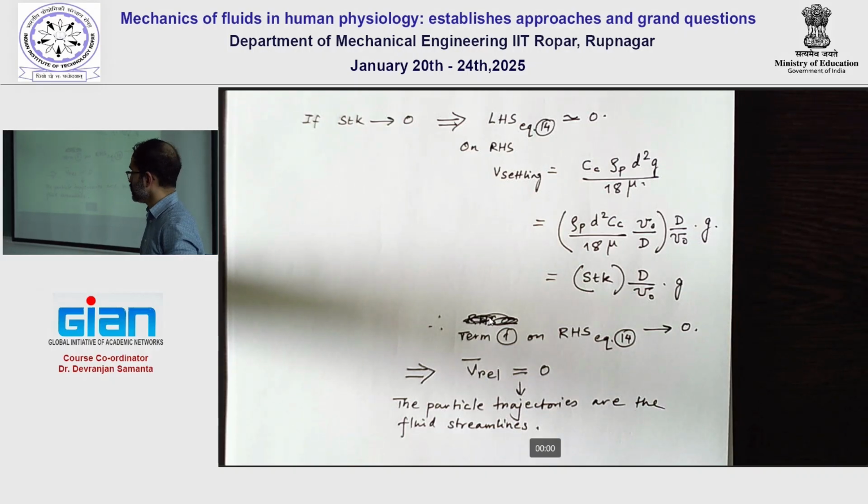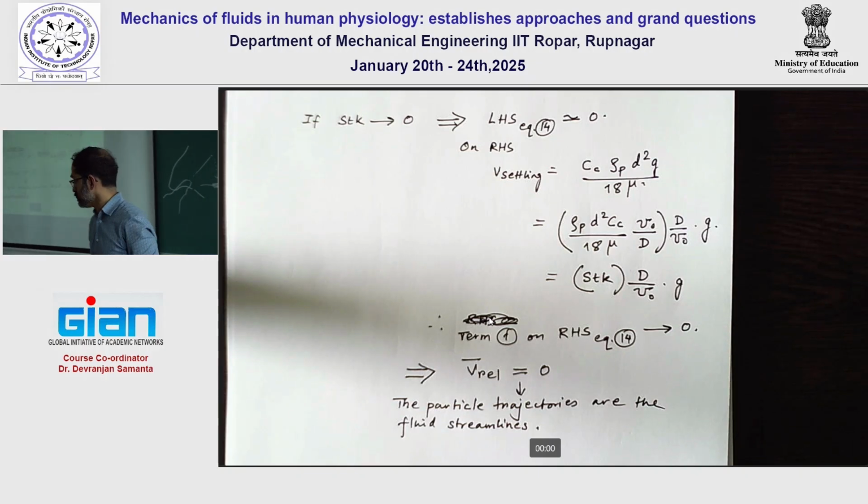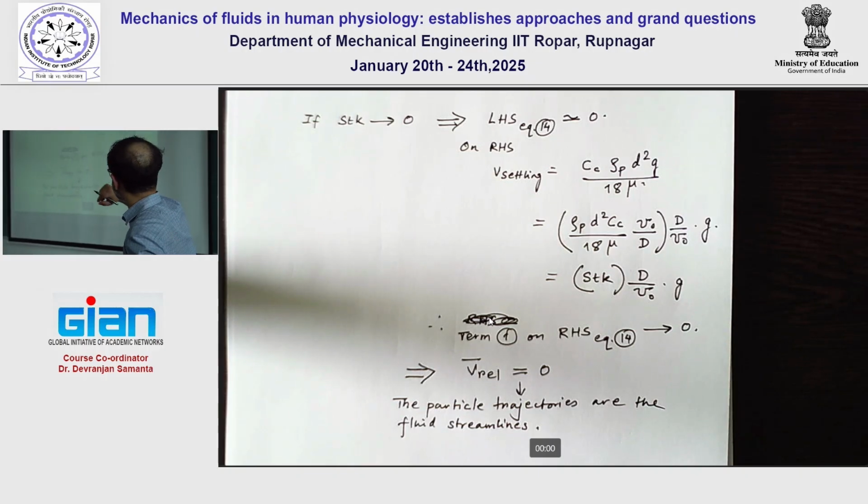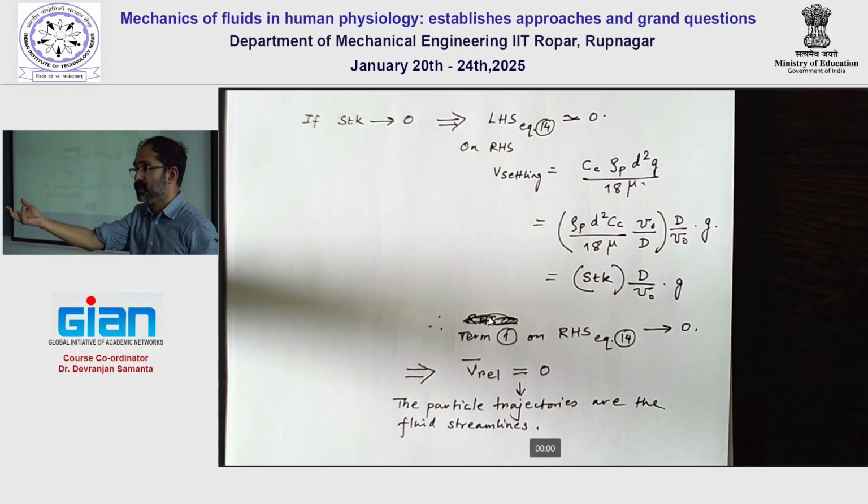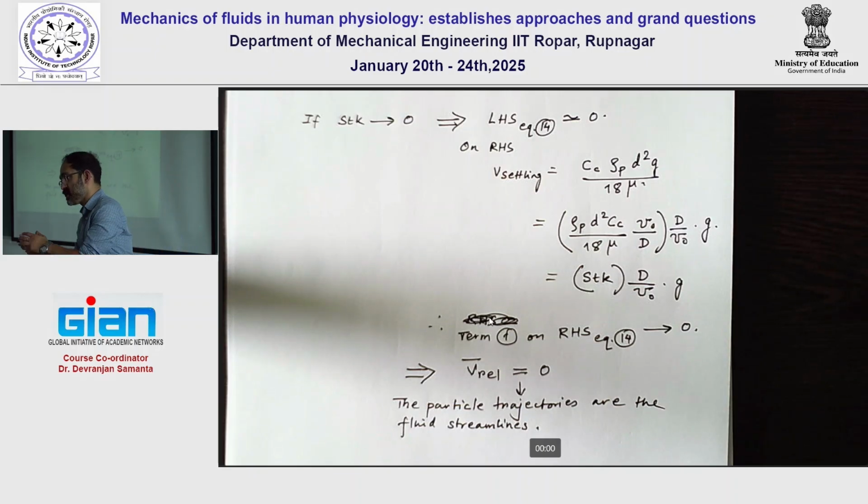So when you are trying to evaluate the Stokes number, yes, the d is important. That's the mechanics work. The material property comes into the rho p. The mu is the mu of the surrounding fluid, so that is not the material property of the drop. The rho p is important, and if you have some kind of polymer, then the rho p is different. Now, whether the rho p can balance the squared effect of the d is a good question.